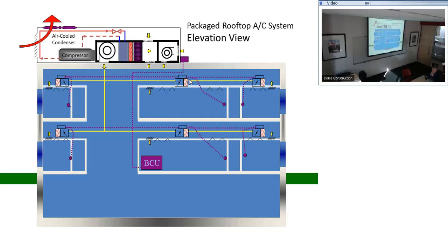So our max value is based on what we think the solar hits us at the same time, with 40 people in here. That's a max. My min is probably either my ventilation rate required for this room. What I'm allowed to do is take it down to a min, and then if I need heat, I turn on my heating valve and then bring it up. So again, I'm minimizing my reheat.